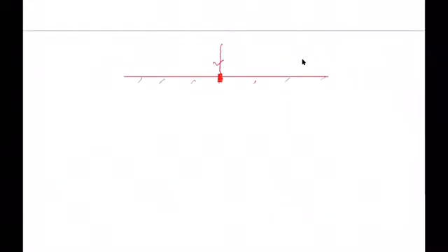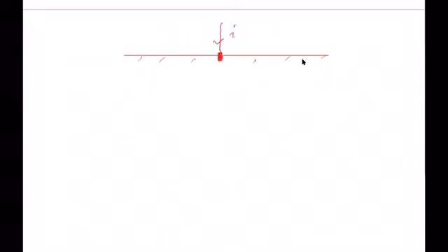If you have a ground like this, and this is a general concept. If you have a current going into the electrode at this point shown there, then this current will move into the soil to an infinite plane, or remote, where the voltage is equal to 0. So the current will go all the way to that point where the voltage becomes 0.